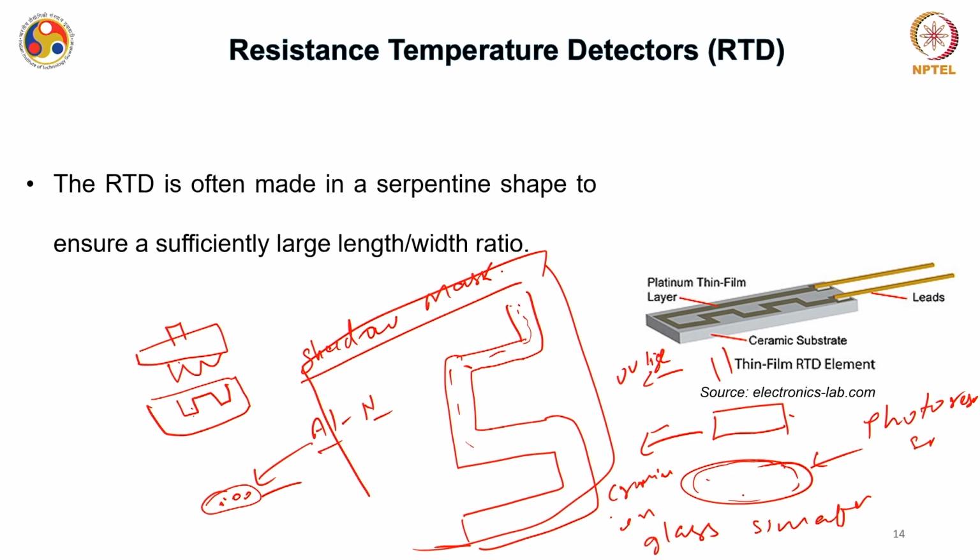Depending on whether it is positive photoresist or negative photoresist, it will either become soluble in a certain solvent, or it becomes hardened. And when I say this becomes softened or hardened, I am talking about the area which is exposed to UV light. If this area is softened, it means the other area is hardened, and vice versa. Okay. And accordingly you can develop it, we call it the development stage, and then you will have this transfer of pattern from this particular mask to this photoresist.